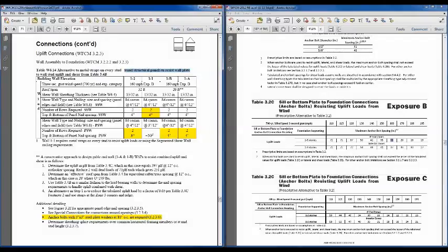I'll point out here that this one particular wall doesn't work in that case. There just isn't enough. We've already got our nails at a pretty tight spacing, I think of 4 inches on center, and there just wasn't enough capacity to handle both lateral shear loads and uplift through the wood structural panels.